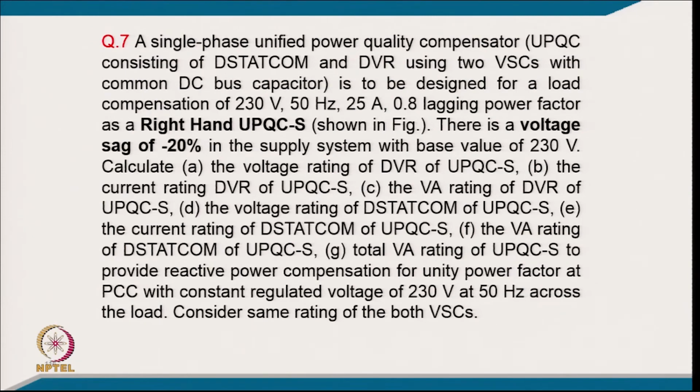So, coming to the 7th numerical example: a single phase UPQC consisting of D-STATCOM and DVR using 2 VSC with a common DC bus capacitor is to be designed for a load compensation of 230 volt, 50 Hz, 25 ampere, 0.8 lagging power factor as a right hand UPQC, and there is a voltage sag of 20% in the supply voltage with a base value of 230 volt.